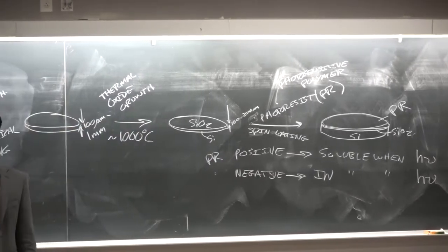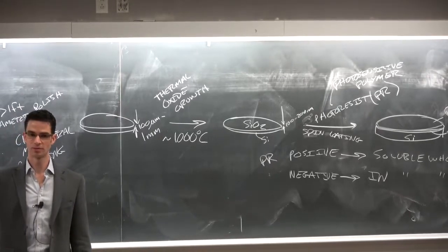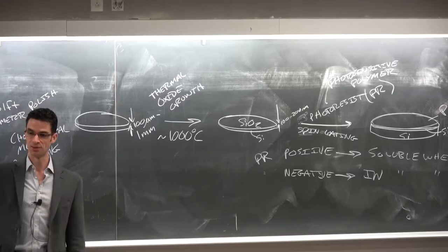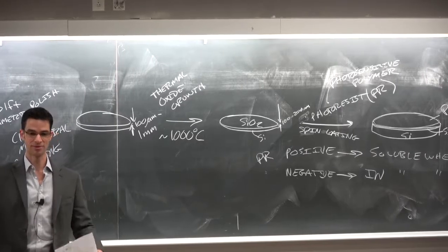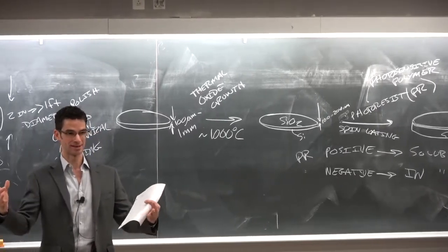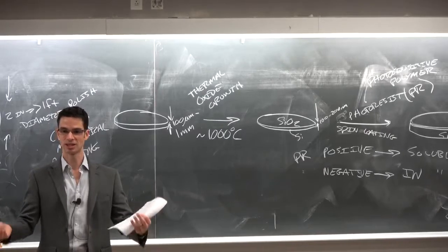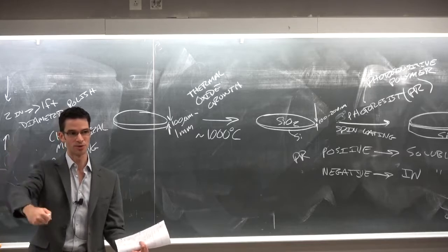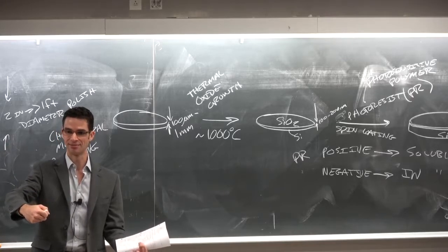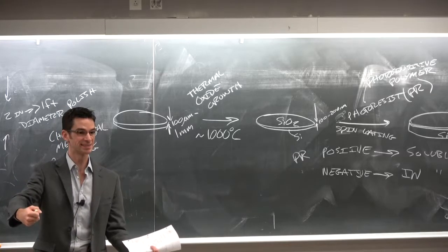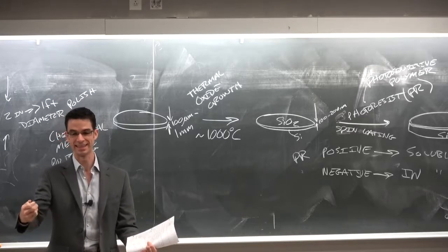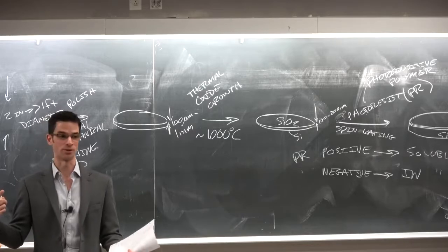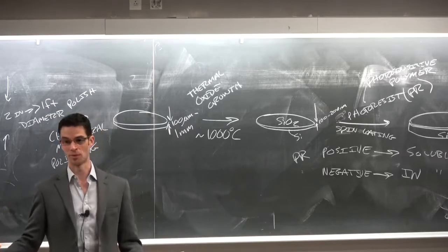You take a solution of the polymer or a neat melt of the polymer, and you put it on a wafer that's on a vacuum chuck, and the vacuum chuck sucks the wafer down to it so that it can't move. And then you pour the photoresist on in a factory. A machine does this, of course. And then it spins at on the order of 1,000 or more RPM.